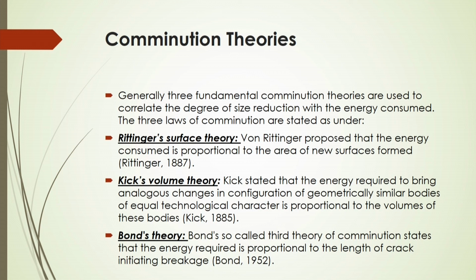As per Kick's volume theory, the energy required to bring about analogous changes in the configuration of geometrically similar bodies of equal technological character is proportional to the volume of these bodies. And as per Bond's theory, the energy required for breaking up into finer ones is proportional to the length of the crack that initiates the breakage to result in the fine particles.